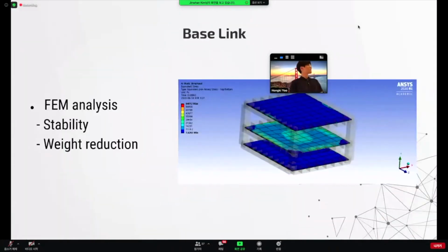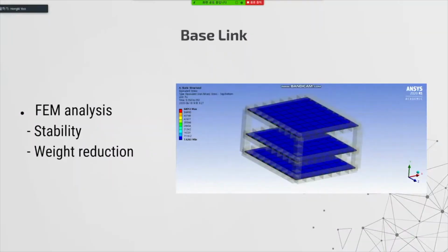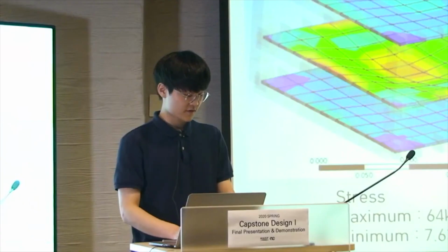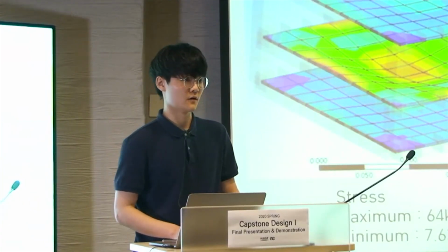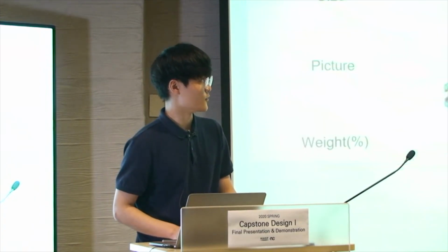We applied FEM analysis to check the safety of the entire structure of the robot and reduce its weight. This is a simple FEM analysis result of the model's body regarding the given values of yield strength and Young's modulus. We conclude that our robot is safe in the Gazebo environment on this structure within its expected nominal forces, exaggerating the forces on the robot.